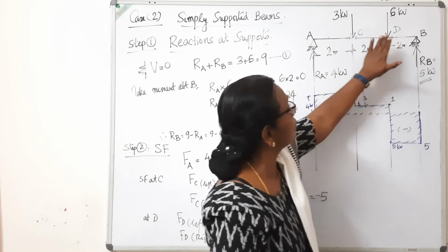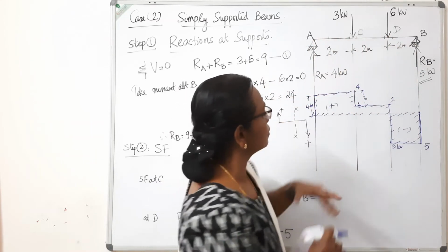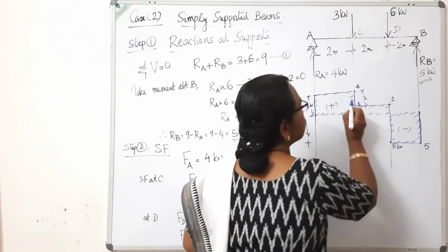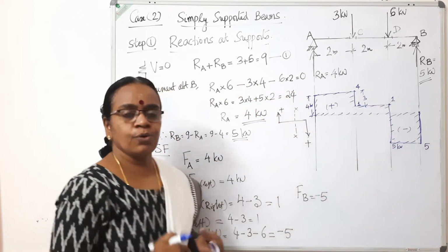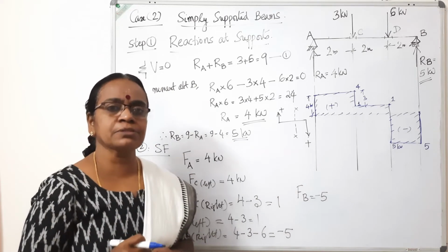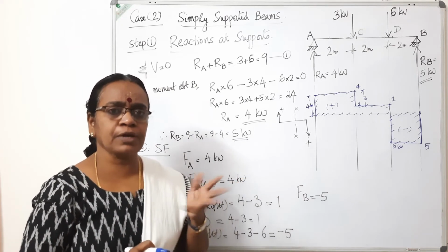Where there is no load in that portion, the shear force diagram is parallel to the baseline. It goes straight when there is no load. If you have this concept, when you go to higher semesters, you can draw the shear force diagrams of any type of beams.